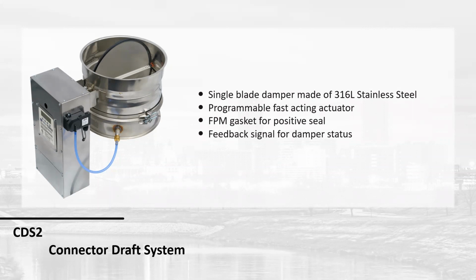It is a single blade damper of all 316L. Fast actioning actuator. We talked about the 2-second actuator. Our system dampers really don't need that type of an actuator. These dampers absolutely do. So we're very quick reacting. It does have a Viton seal for positive shutoff. Available for, I just saw the question come in, 4-inch up to 16-inch with our single blade dampers. And then we do have feedback signal. Again, Modbus on board, so we can send all of that information to the BMS to tell you exactly what the boiler is doing, or the boiler venting is doing at all times.